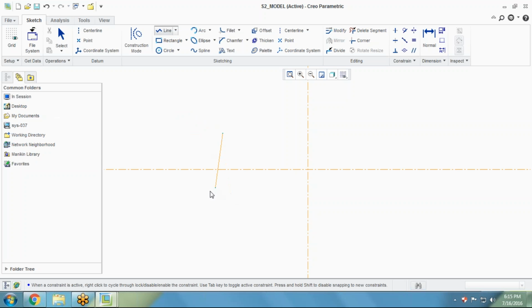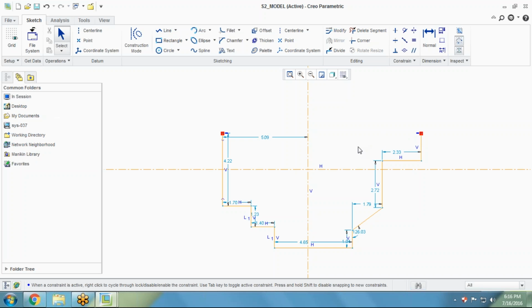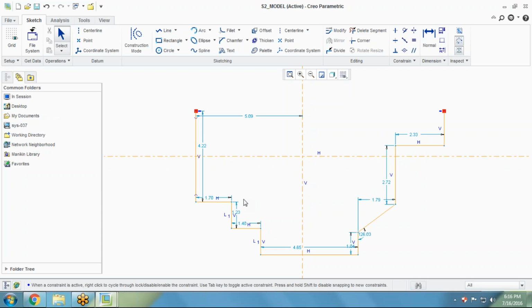So first of all I'm just clicking anywhere on the screen like this. Second line, third, fourth. By this way we can get the geometry of our need. If I specify some angle here, you can see we cannot define the dimensions along with the object creation. After that, once we have worked and gotten out of the command, we can see the dimensions shown, and all these dimensions will be weak dimensions, and we have to make them permanent, or strong, basically.